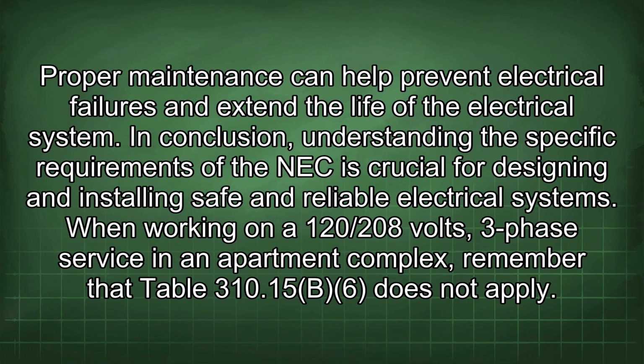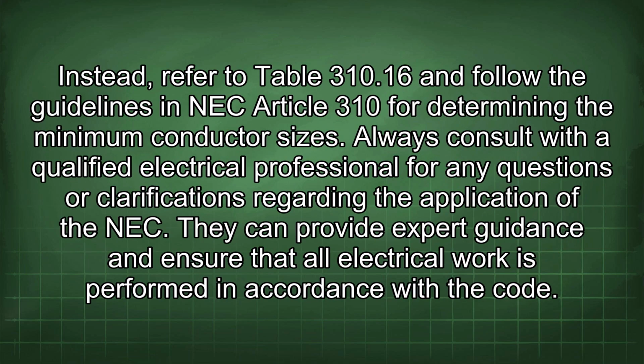When working on a 120/208 volts, three-phase service in an apartment complex, remember that Table 310.15(B)(6) does not apply. Instead, refer to Table 310.16 and follow the guidelines in NEC Article 310 for determining the minimum conductor sizes. Always consult with a qualified electrical professional for any questions or clarifications regarding the application of the NEC. They can provide expert guidance and ensure that all electrical work is performed in accordance with the code.